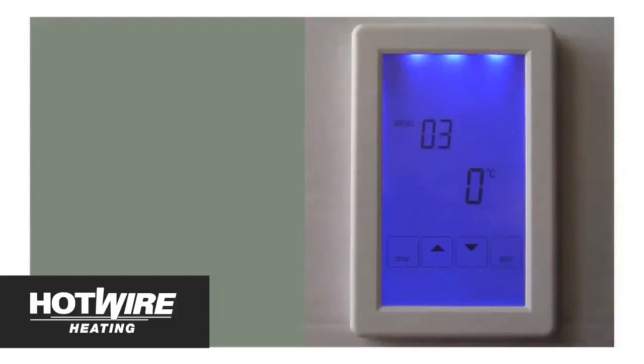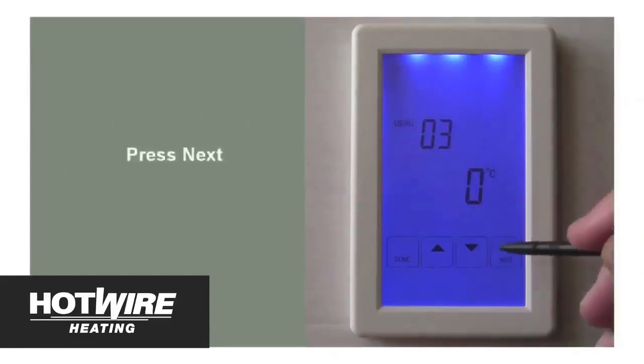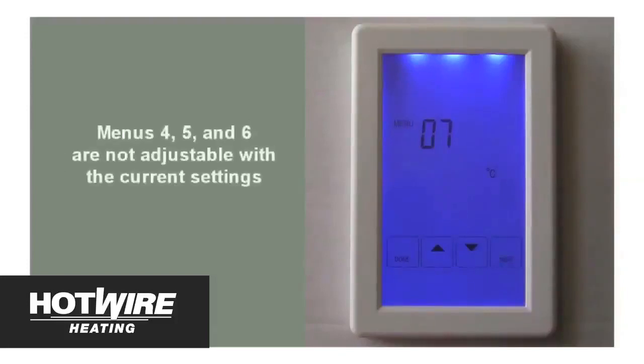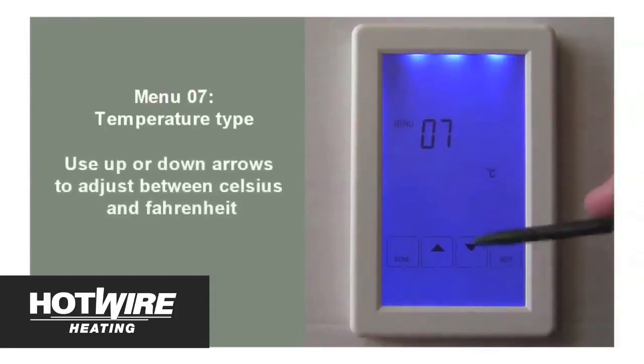Menu 3 is used to calibrate the unit's air temperature thermometer. Simply use the up or down arrows to calibrate the unit's thermometer up or down. Since we are only using the underfloor temperature sensor, we will leave this at 0 degrees difference and press Next to move to the next menu. Menus 4, 5 and 6 may not be available for programming depending on your unit's installation, which means the next option will be menu 7, which is used to change between Celsius and Fahrenheit. In this case, we will select C for Celsius and press Next to move to the next menu.